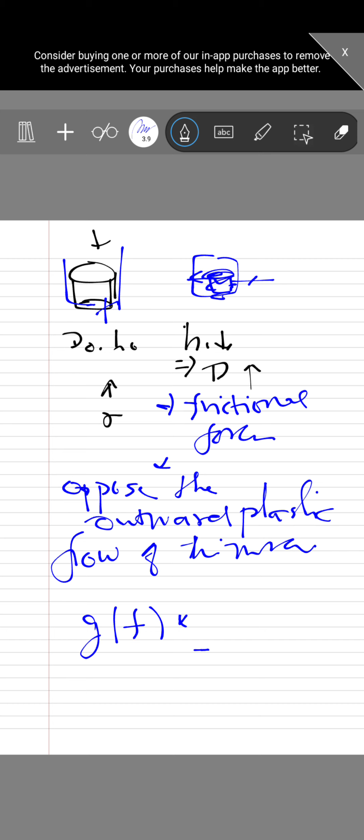More often it is at the middle where the flow is undisturbed, whereas where the specimen has been held, at the anvil, there the frictional forces are the highest. In the middle it's quite free. So we get a barreled specimen profile.